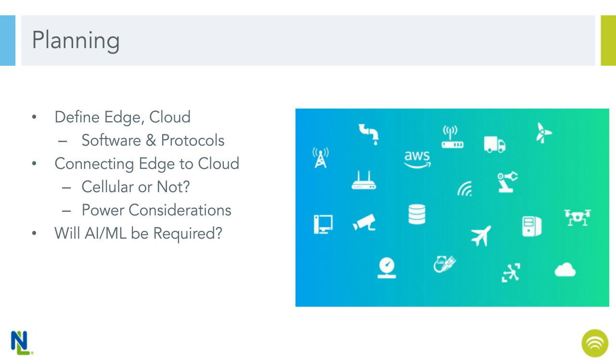Yeah, I think many of these things come down to cost too, right? If you have a more expensive edge device, like a sensor, and it has greater capability, can do TCP/IP and stuff like that, then you could put MQTT right there. Or as you mentioned, you could put it at a gateway and have a much less expensive, much simpler sensor that just talks to the gateway, and the gateway forwards it using MQTT. So I agree that it really depends on how you're going to configure your system. You could actually do it pretty much anywhere, right?